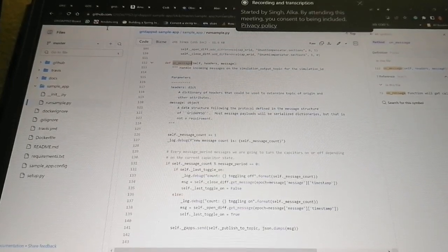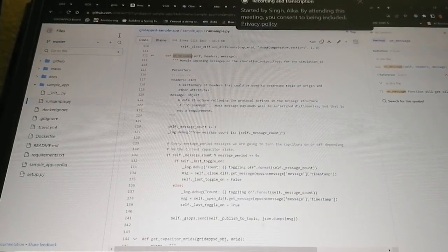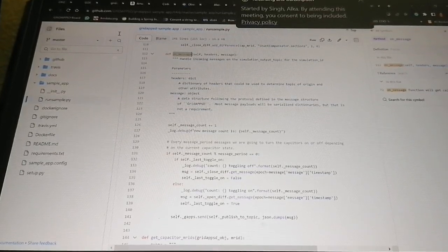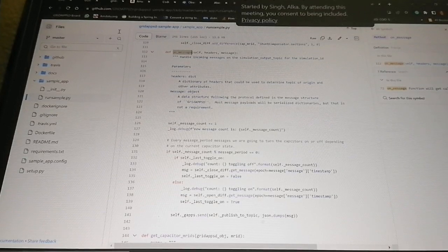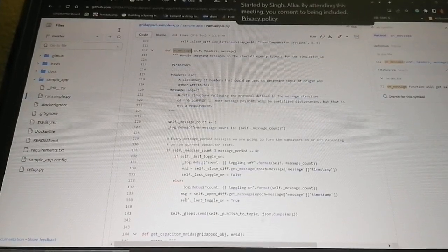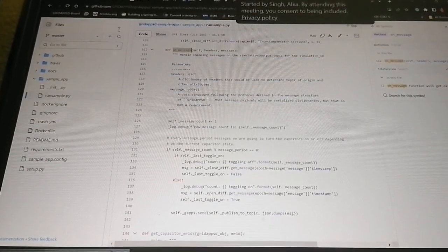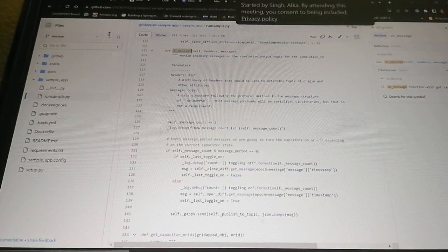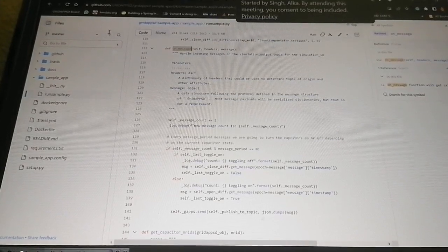Yeah, so that's why I was showing you this sample application. This sample application works with IEEE 13, 123, 8500, 9500, or basically any graph-based data in the Common Information Model data format. It doesn't change. You can run it with any model. The reason being, we are using a standardized data set and a standardized message structure.